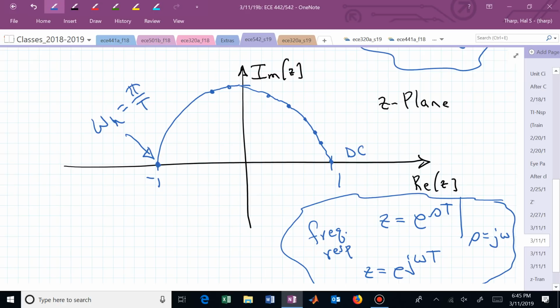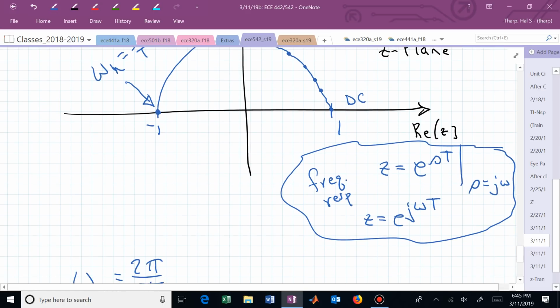And that's another justification, hopefully, for why these high frequencies map to this z plus 1 factor. The z plus 1 factor corresponds to values of z equal to -1, and that's when we get over there at the highest frequency in the z-plane. That's why we're mapping these zeros at infinity in the s domain to factors of z plus 1. We may not want to map all of them. We may want to preserve some pole-zero excess in the discrete equivalent, but we can play with that.